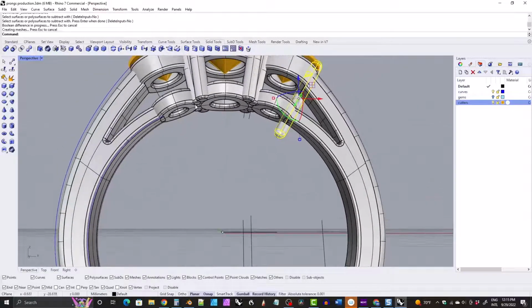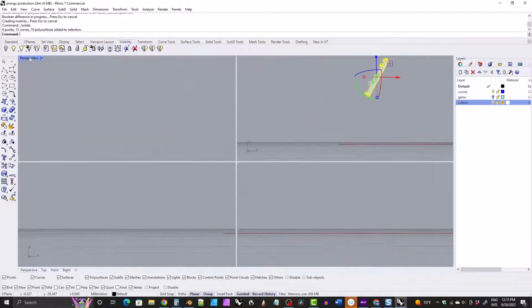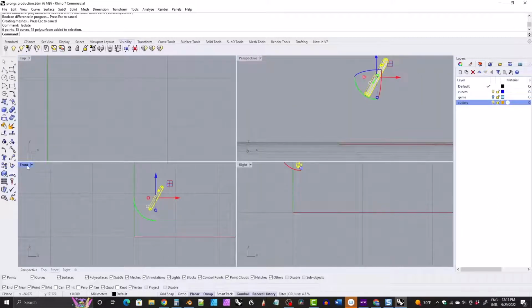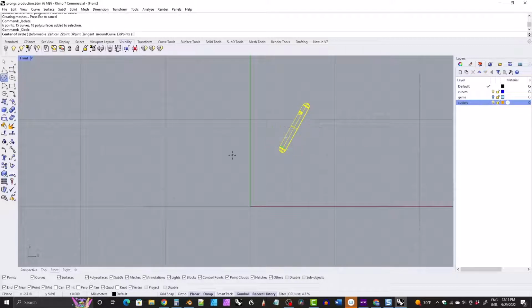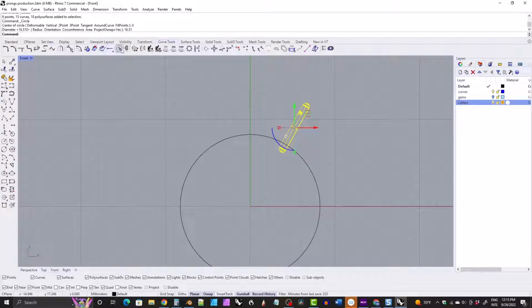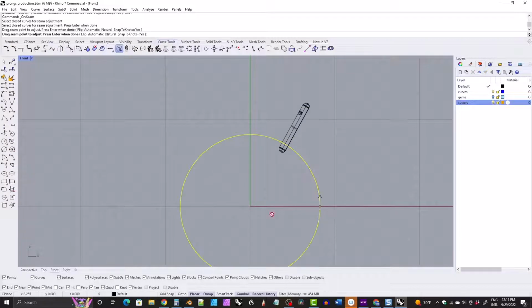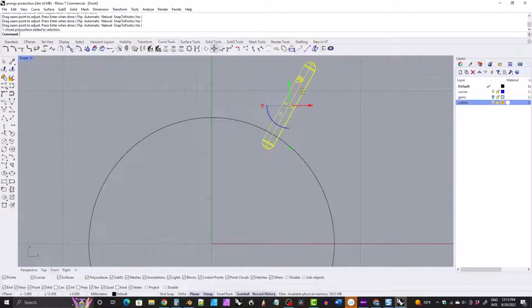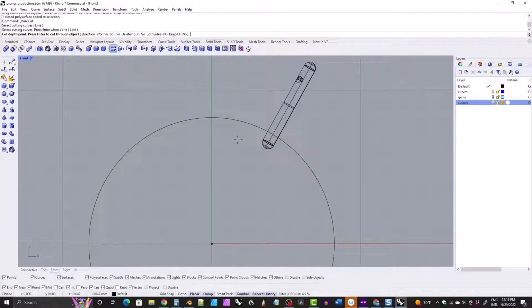So I think we've lost our sizing, finger size or sizing circle again, so we'll just have to lay in a new one of those. All right, so we'll just clip the bottom of this off with the wire cut tool and add a 0.15 fillet on the bottom of that prong.